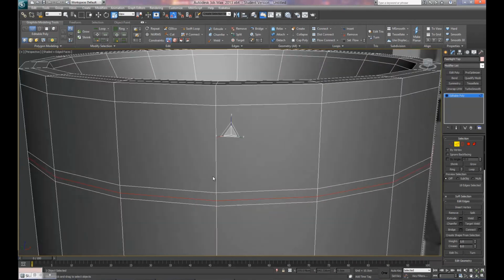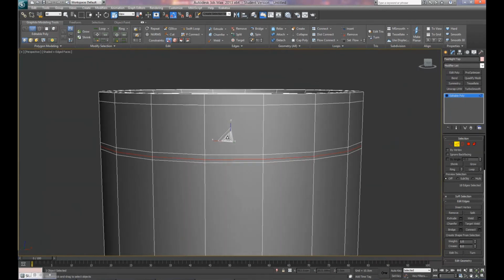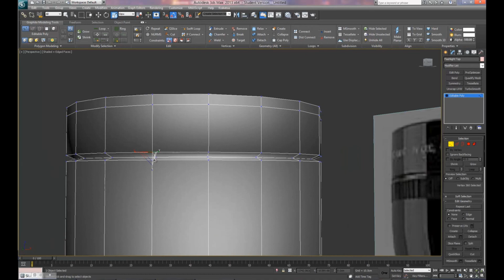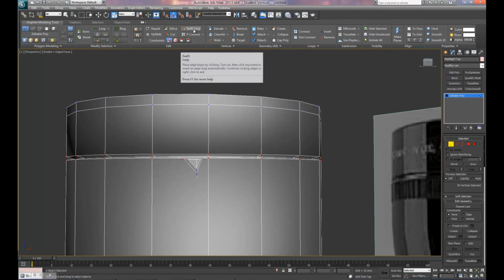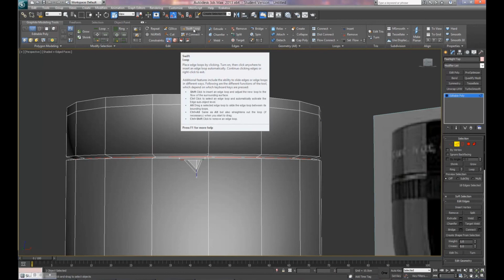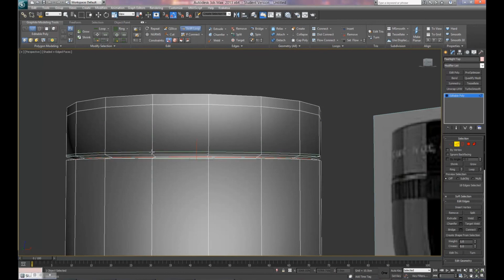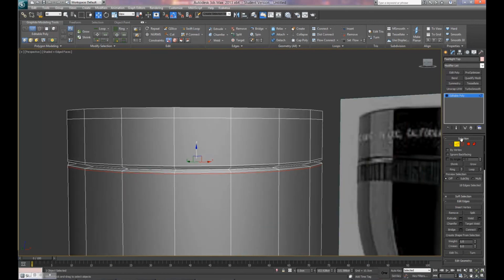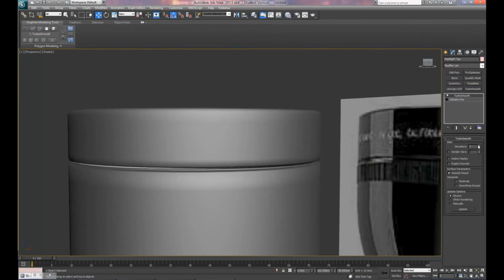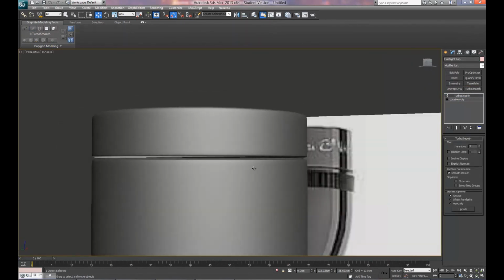So now, going back to the lesson, if you have this middle line selected, scale that in. Click on these vertices right here. Click the one next to it with Shift click, and it'll select that ring. Same down here, Shift click. And then in the Z axis, tighten that up a little bit. We're going to go back into edge mode by pressing 2. Click Shift Swift Loop. And we're going to add some edge loops there to keep this shape minimalized. If you smooth it, you can see that now we've got a nice little flashlight divot.